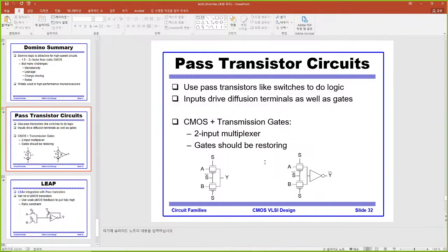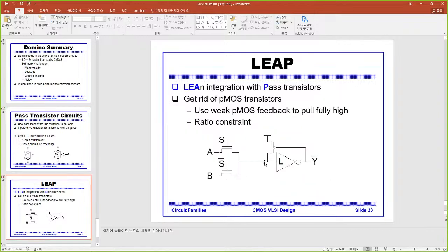This is a reliable circuit, and they're very simple compared to the multi-level gate design. Using only NMOS devices, NMOS logic is also sometimes used, but in most cases this kind of logic style is favorable in a low VTH process.